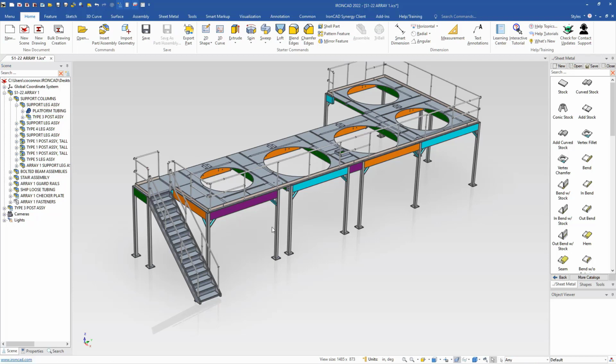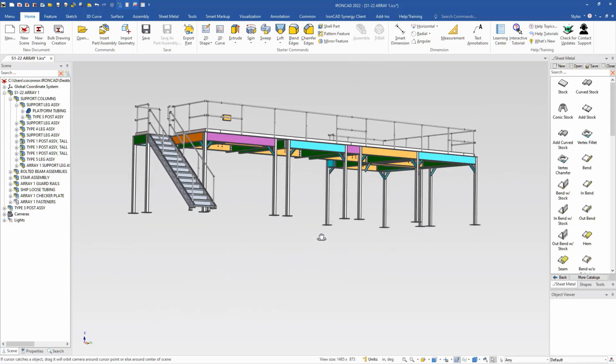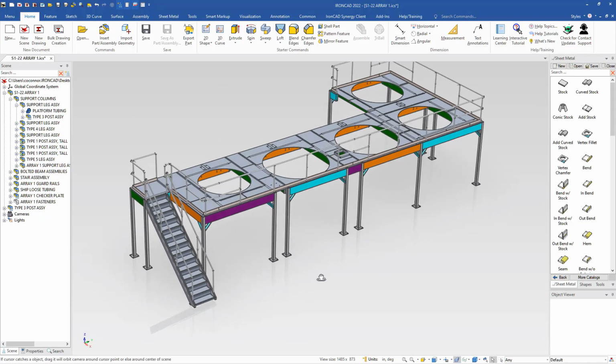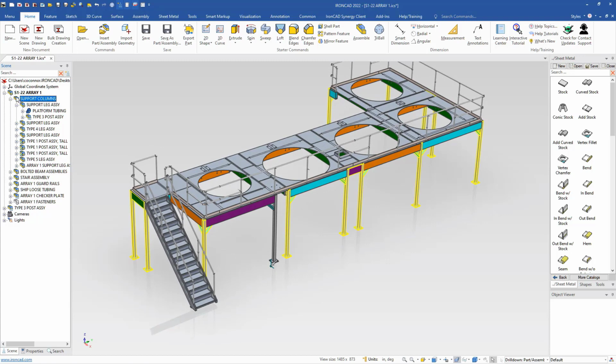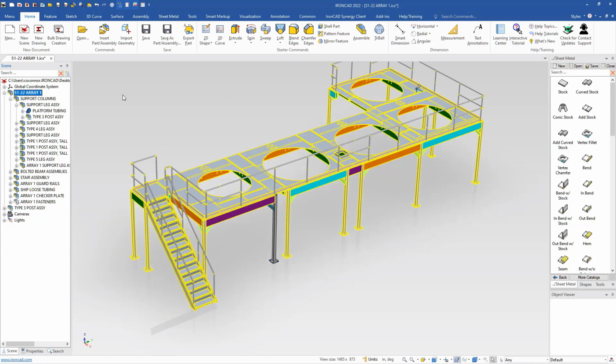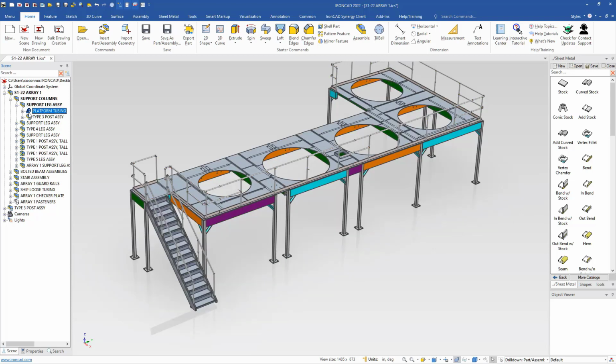Now, one thing to note is when you're doing a Control-V, it doesn't paste it in place, it pastes it in the scene based on the orientation of your model. So it would actually use the structure or the anchor location of your assemblies to reorient or restructure the path for that particular part, which is not what we want to do in this particular case.